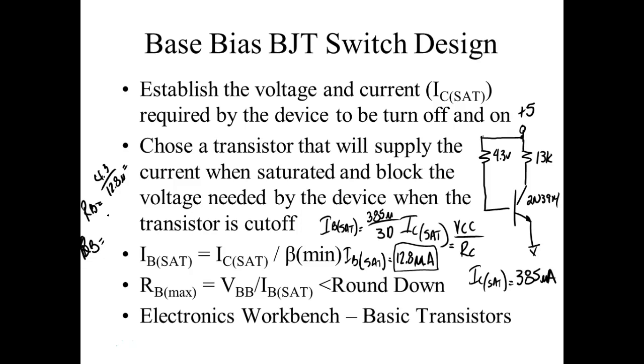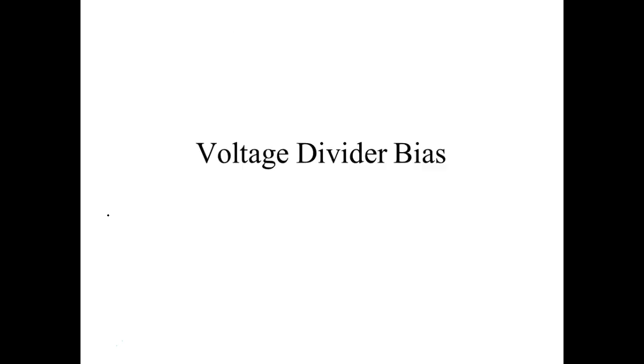We could do this another way, by the way. What's nice about saturated switches is we can do it like this. I could come over here and have my transistor. Let's say I'm going to run a relay. We'll talk about this in a minute. My relay is a 12 volt relay at 100 ohms. Then I'm going to run this through a transistor, and I'm going to put a diode right here, by the way. But I'm going to run this off a 5 volt circuit. We'll show y'all that when we get back off break.